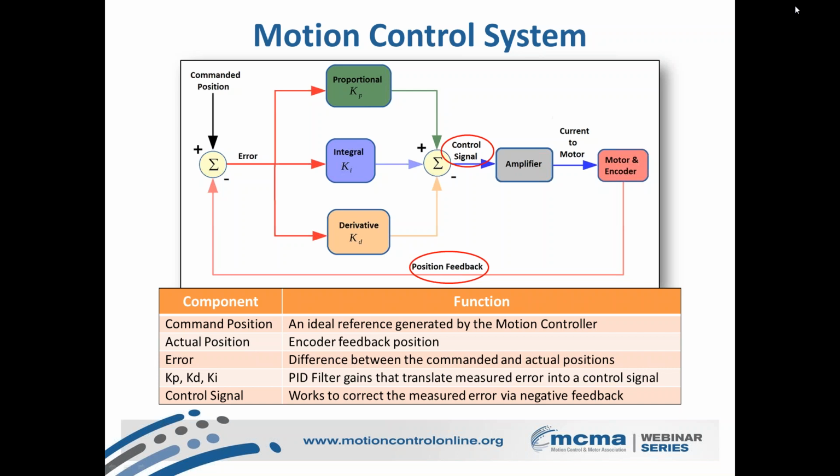Your control signal at your motion controller is simply a voltage that's being generated, that the amplifier then sees and turns into a current that goes through the motor coils. And then the feedback from the encoder, again, is just a voltage seen almost instantaneously at the motion controller inputs. And so there's no latency in the system. There's no chance for race conditions or for information to get mixed up, essentially.